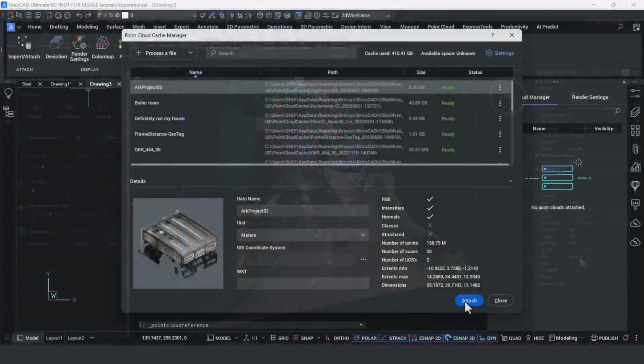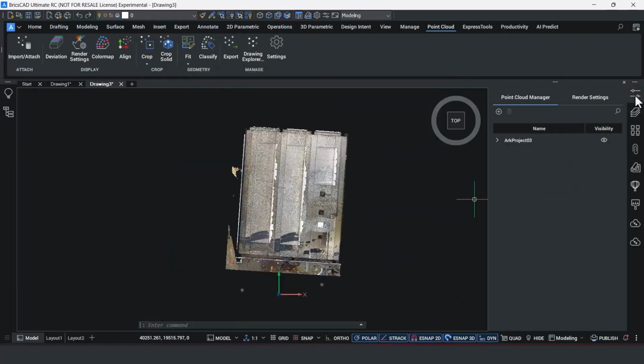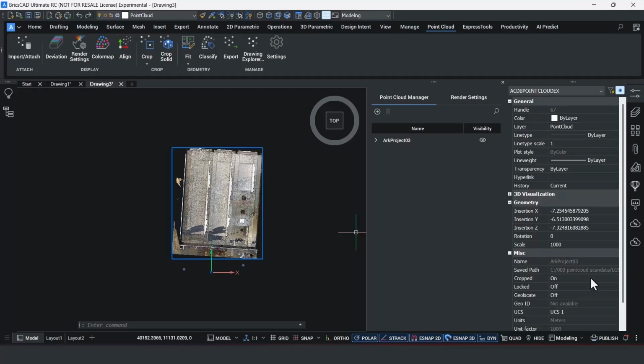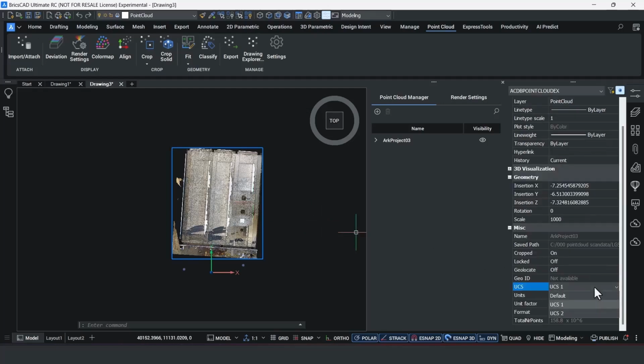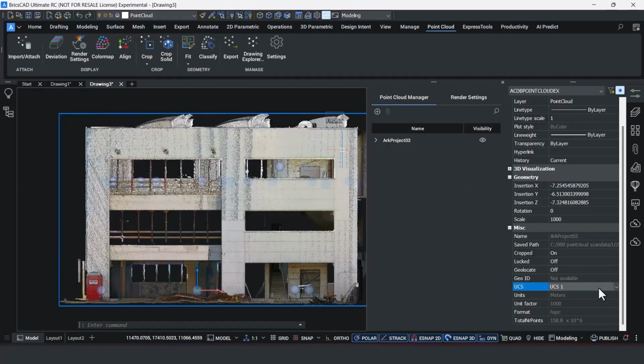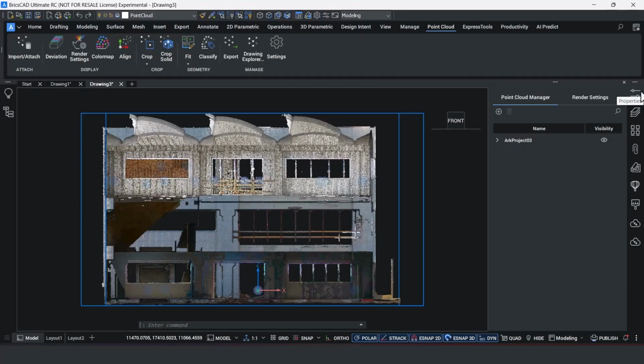Another difference with LGSX format is that if you've scanned with multiple user coordinate systems, these will be available when you're working with the point cloud. Now remember, user coordinate systems are set within the Leica Geosystems software, whatever you're using there. You don't set them in BricsCAD. But if those have been set up, then what we've created in V26 will make it easier to handle complex geometries like multiple floors or sloped walls, and it improves accuracy for measurements. It also streamlines and facilitates modeling and design.